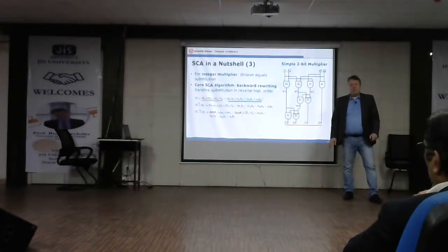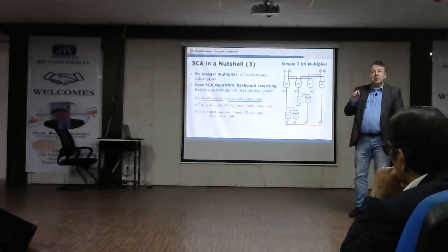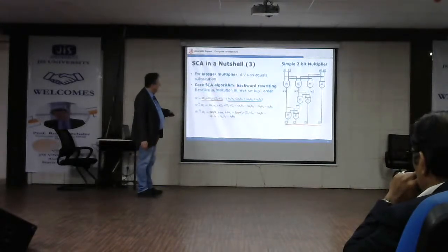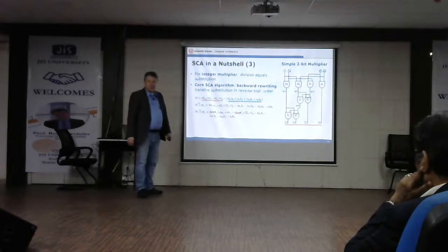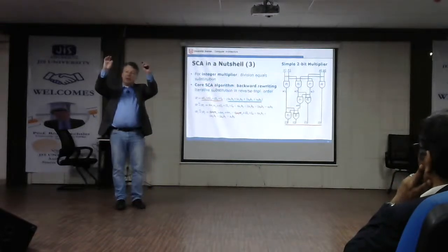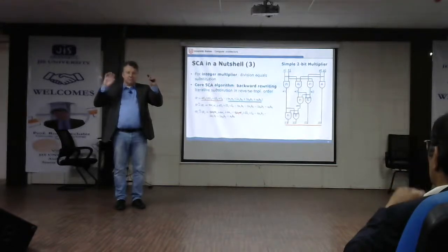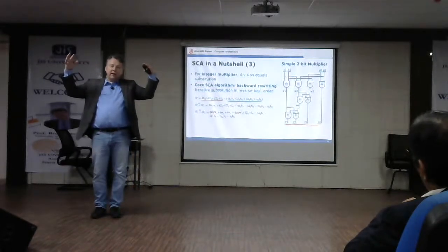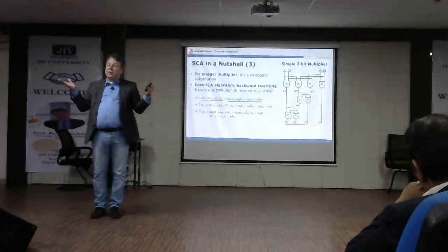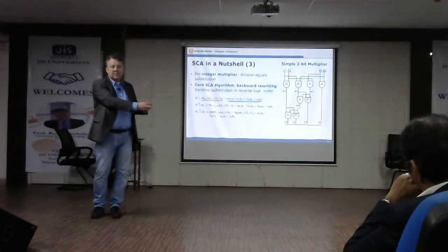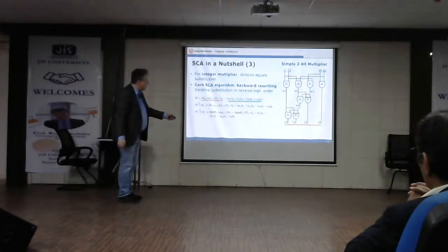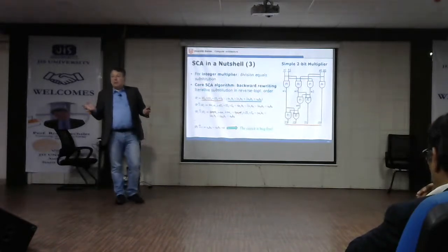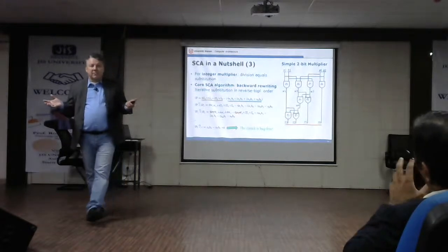And if we do so, what we see, this is the most relevant observation. Yes, for a small example, here we have 8 times W1, W4 in positive form, and here we have it in negative form. And this means we generate something and that gets canceled out. That's important, because that is exactly what formal verification does. It generates these terms, and now they reduce, and if it's a correct circuit, it will reduce to 0 at the end. And when we continue this process, all the steps up, then we'll see that this is really 0, and this means this is really a multiplier. It's bug-free.